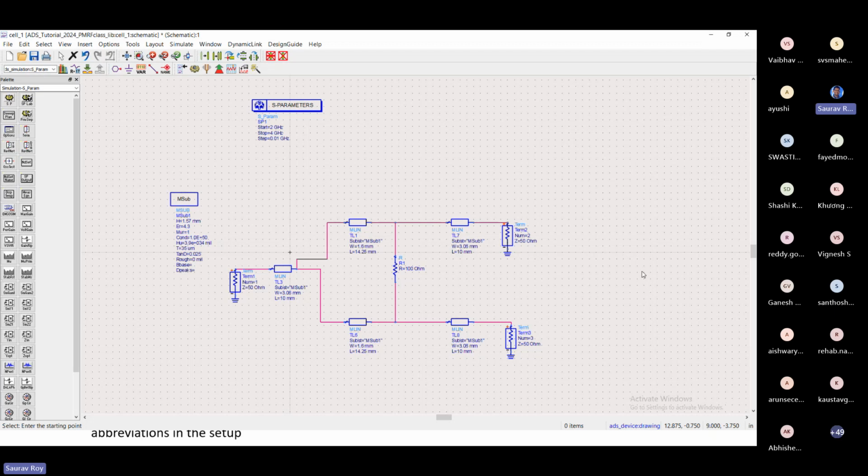See, for the 50 ohm line, as I told you, the phase does not matter generally. Just for the port connection, you need some length. You can do a tuning to see what gives you optimum matching. We can take any length, sir? You can take any length, yes, as long as your matching is good. For the Wilkinson power divider, the design parameters do not say anything about the 50 ohm line length. That you can take of your choice.